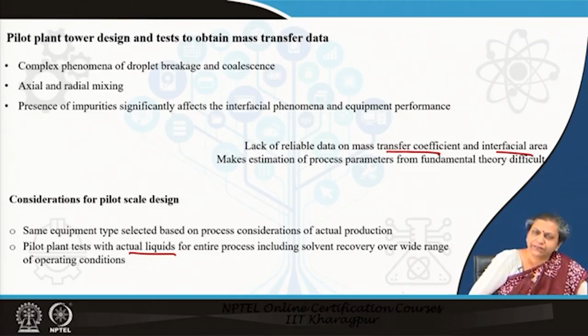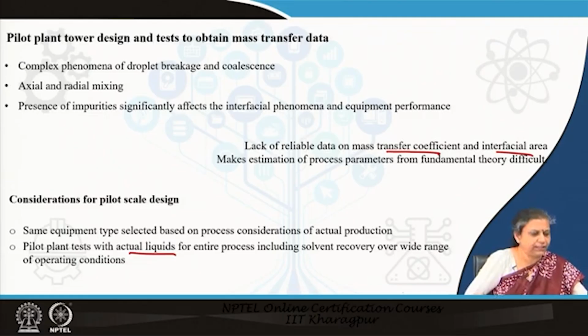So, even for generating data for the pilot plant, we just need data on the mass transfer coefficient and interfacial area, which has nothing to do with the solvent recovery. But then also it is advisable that the pilot plant tests are performed over the entire process, including both the extraction as well as the solvent recovery over a wide range of operating conditions.